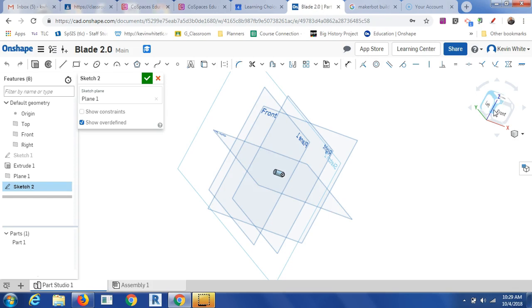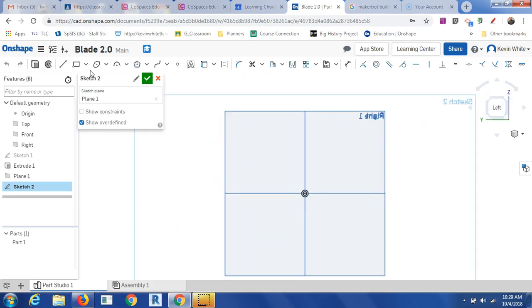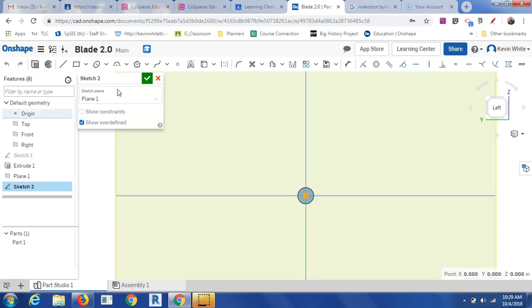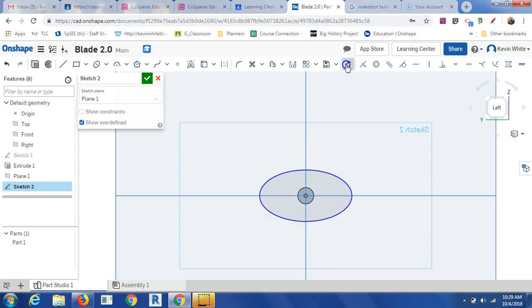So I'm going to go ahead and go to my side view now. And I'm going to go to the ellipse tool. Make sure you have this one selected, not a circle. And I'm going to go ahead and start in the middle, so you can zoom in if you'd like. Click one time, pull out to the right, and notice how if you pull up and away, it'll kind of get off of the axes. So you want to be lined up so it snaps to that plane. And then you can go ahead and click again up here, and you don't have to worry about dimensioning. I'm going to show you how to dimension it. So go ahead and set that up first. Now what you're going to do is click somewhere near the top and somewhere near the bottom again, and that will give you the dimensions from the top to bottom. And we're going to set that equal.